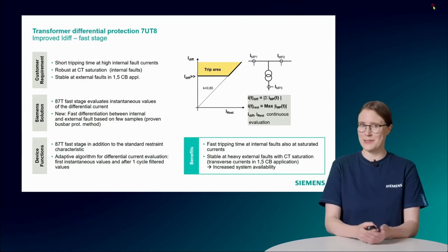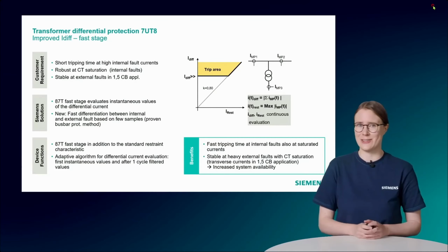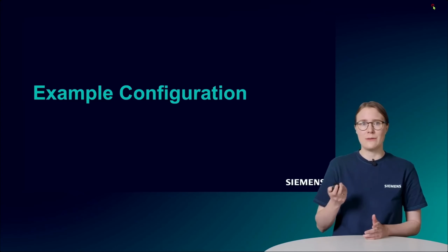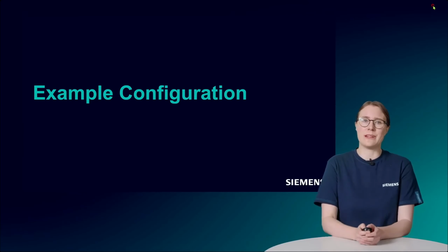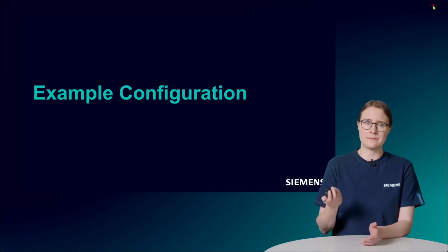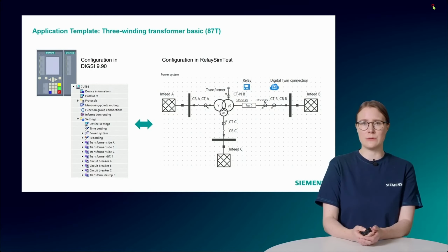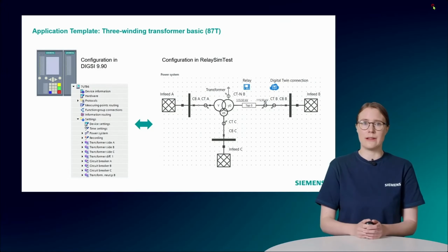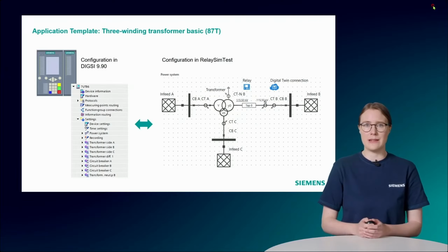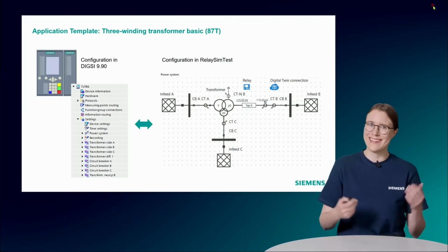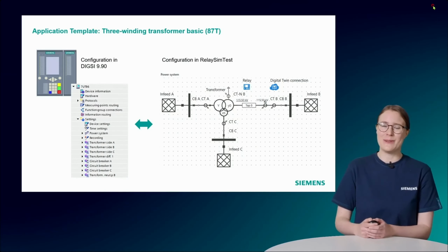Okay, so much about the theoretical part of today's session. For the demo part, Lukas and I prepared a relay configuration together. The device that will be simulated in the digital twin is a 7UT86. We decided to work with the templates or examples that we offer in DIGSI 5 and in the RelaySimTest library to make things easier for us and, more importantly, for you when you want to do some tests on your own.